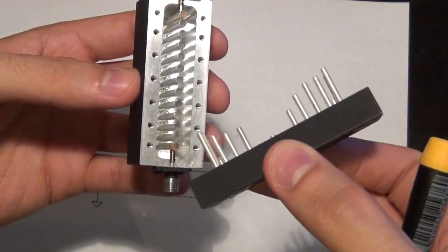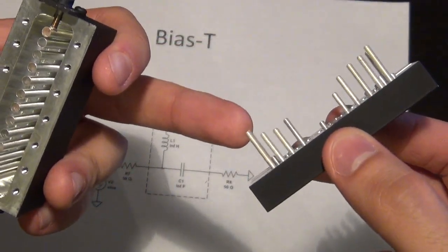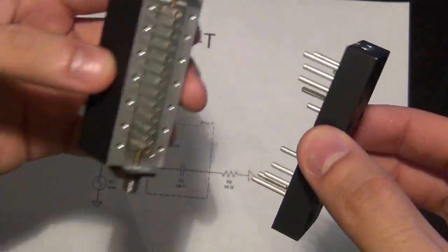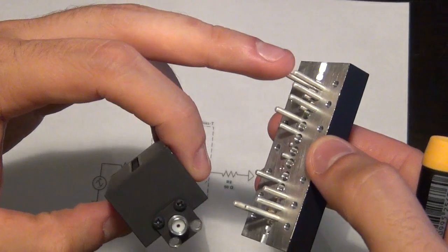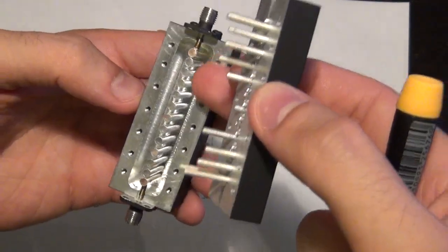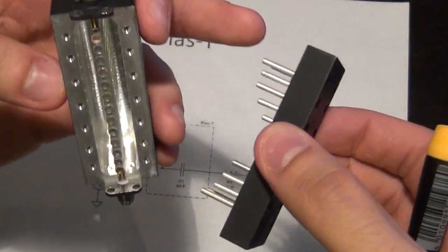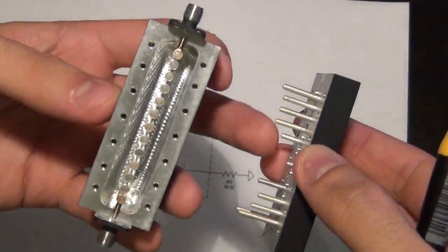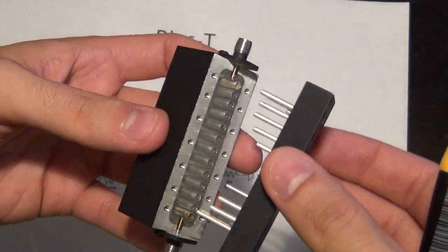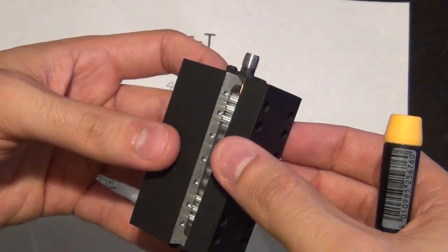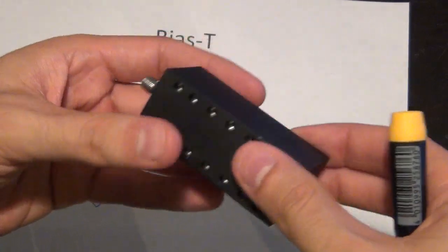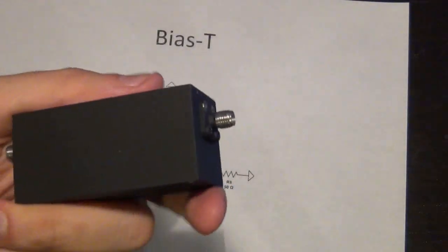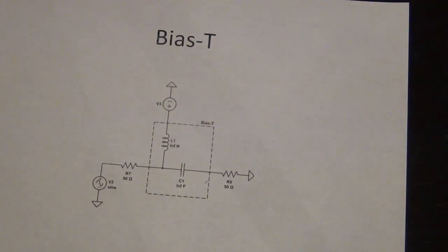But on this side you have this various length of screws that they have carefully screwed in and then cut to the proper length. So when you put this in here, the interaction between these poles into the cavity will create a certain frequency response, and you can model this in a 3D modeling tool, and you can calculate exactly how big these need to be and where they fit and so on. So this is carefully placed inside here, and it will fit between those poles that you saw, and it will create a certain frequency response, and we will talk a little bit about that in a different video.